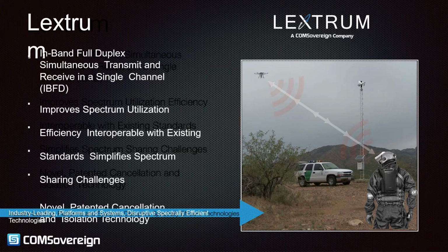The passive self-interference cancellation method is fundamentally different by trying to eliminate the multipath interference before it's seen. With optimized antenna patterns, we have seen an additional 65 dB or better of attenuation in this domain. Coupled with the baseband and RF techniques, it's now possible to achieve the necessary link margins for terrestrial systems.